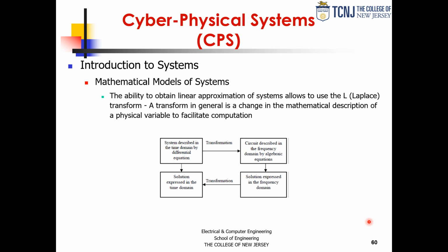A lot easier. Okay? A lot easier. And that's the result of this diagram. Basically, you went to the frequency domain, did your manipulation, which in this case is just taking that band and zeroing everything else out as a filtering operation, and then go back to the time domain.